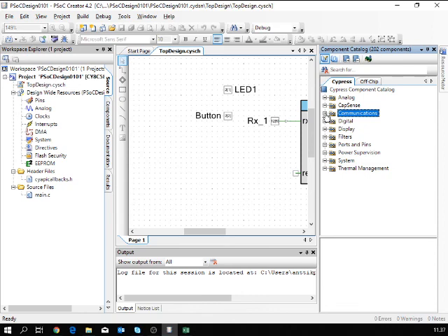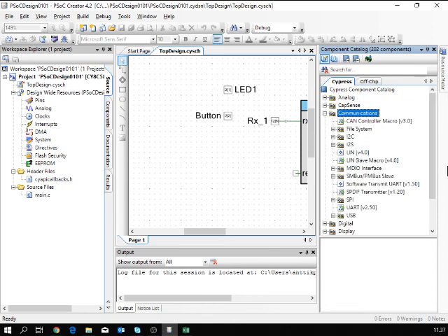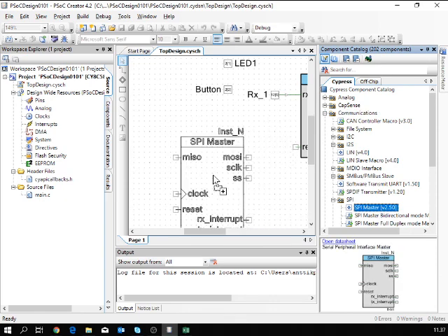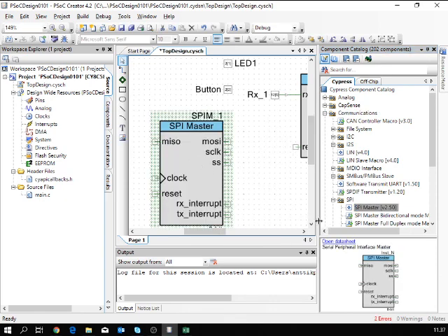modules, or not modules, these are components. Where do we have them? There's the SPI component under that one, and there's the I2C component under that one. So, the SPI component: basically you would need that SPI master. That's the standard SPI controller with master in, slave out.